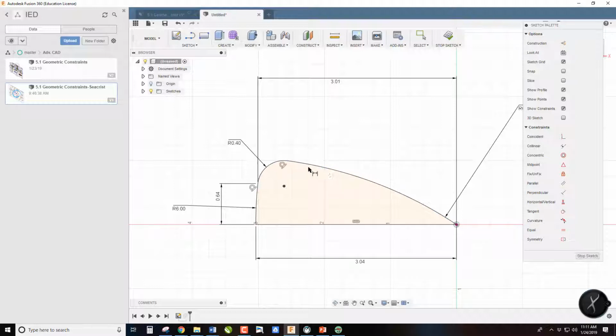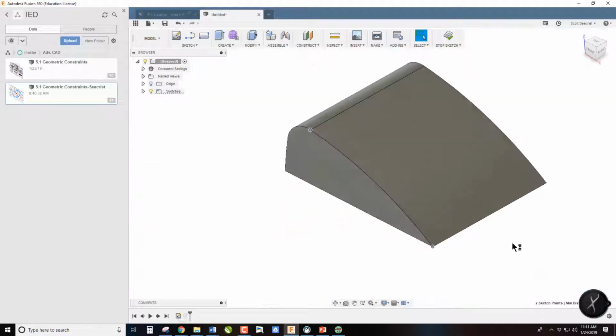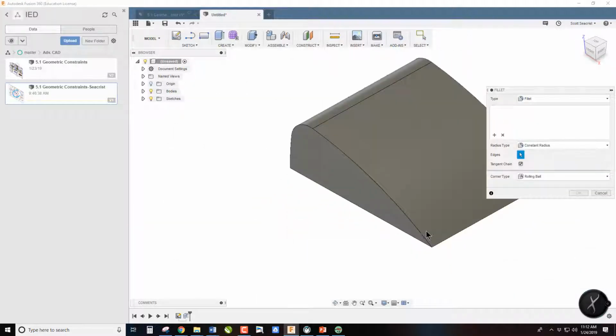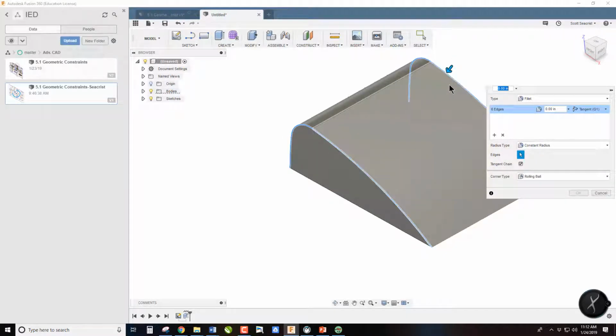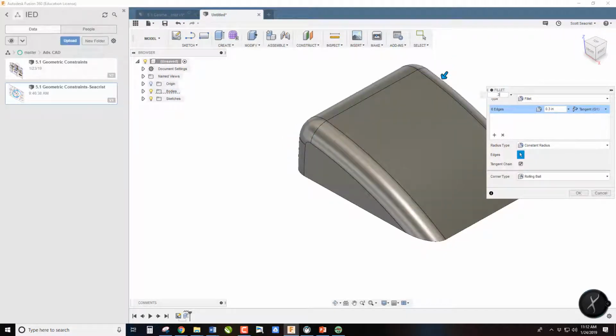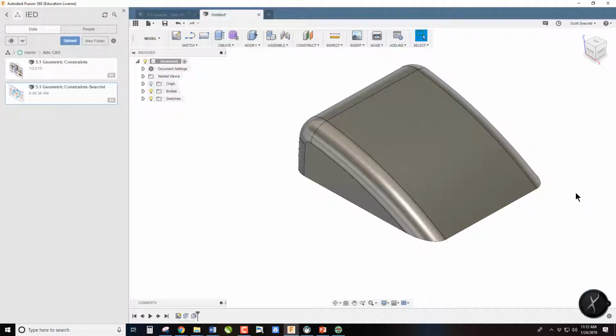The way you can tell is if I hit dimension and select this point, you'll notice it went from 1.0 to 0.996, or 4 thousandths of an inch smaller, which is negligible on this windshield. Now when we hit stop sketch and we hit fillet, we can select one continuous curve, and we can do those both to 0.3 and click OK.